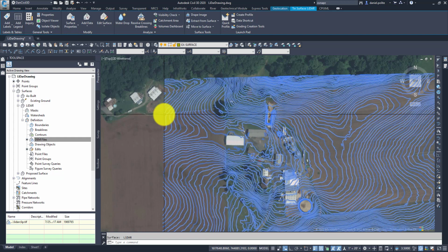And then you can create another LiDAR outside of that if that reviewer would want to see more topography outside of that area. I guess my point is just make sure that whatever you're doing, that one, you get the okay from the area engineer that using LiDAR is okay for the design, and two, reducing or simplifying that surface is okay to do if you're just doing a broader view of that actual design.